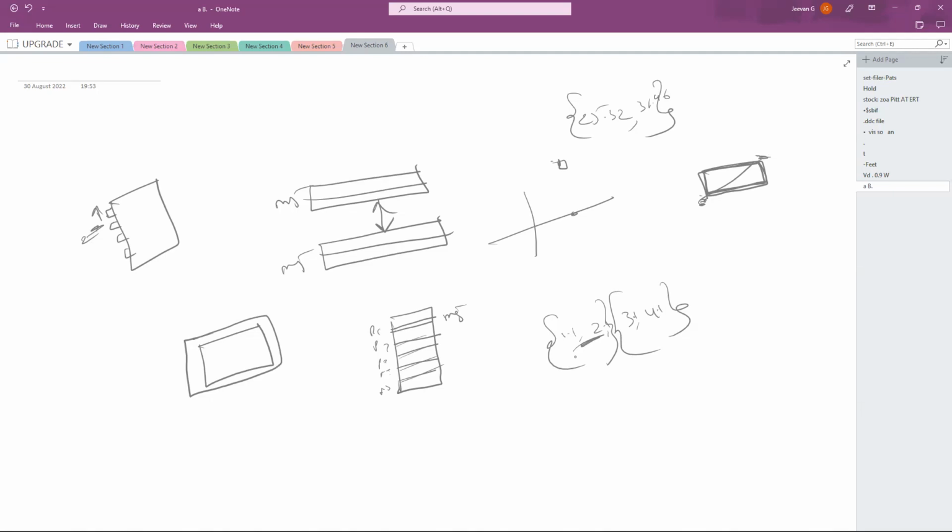For example, this is a clock. Here it is coming. This particular net name will be clock A, for example. Here you have generated one more clock. This is M5 only, this particular metal layer. This is M5 only. Somehow it came like this and this got shorted.